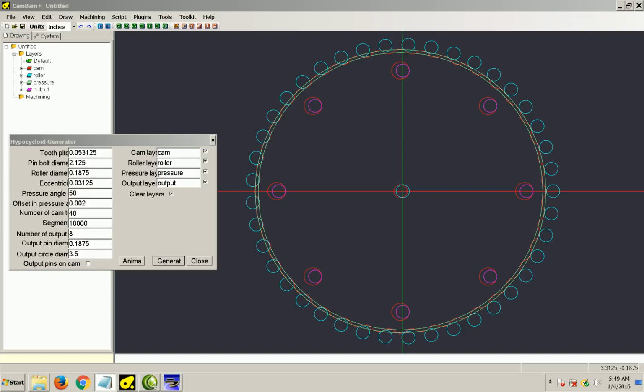The third variation I came up with was to use a ring insert in the housing that had a pin profile built into it. This way I could change the gear ratio without having to make a whole new housing.